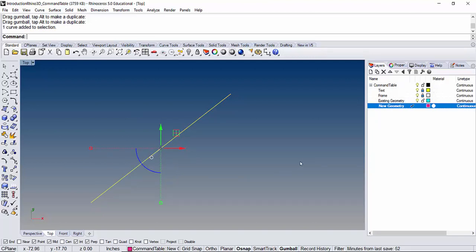So select your curve. Instead of typing points on, we can type P on and P off, points on and point off. So select this again, point on, and you'll be able to move any of these ends around. So a line is a 1-degree curve. It's a type of curve, a 1-degree curve, because it only requires 1 point for it to completely change its shape, its length. Does that make sense? So it's just based on how many points of influence it has.